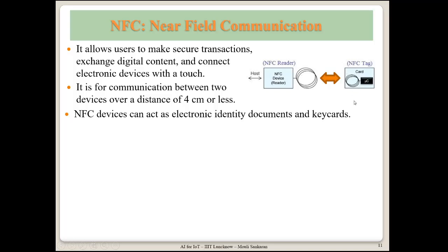I will talk about RFID to explain how the information is transmitted. The reader sends an RF signal, a radio frequency signal, which is picked up by the antenna here, and then it knows that it is supposed to send back some information. There is a microcontroller which is energized by the transmitted energy. When the RF energy goes out, it induces some current here and powers this also, because you don't need a battery here. It can be a passive device, and it sends back some known information which is stored in an SRAM or an EEPROM.